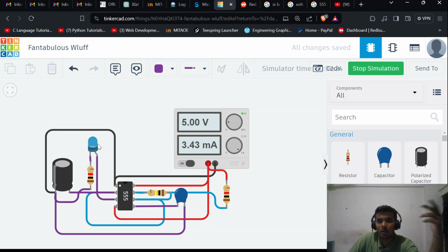We will learn about potentiometers. Some of you who know potentiometers, we can replace one of these resistors with a potentiometer. Using that we can change the frequency while running, by changing the resistance, right. So now the question for you guys is: if I want to make a flexible 555 circuit, that means I want to be able to change the frequency.